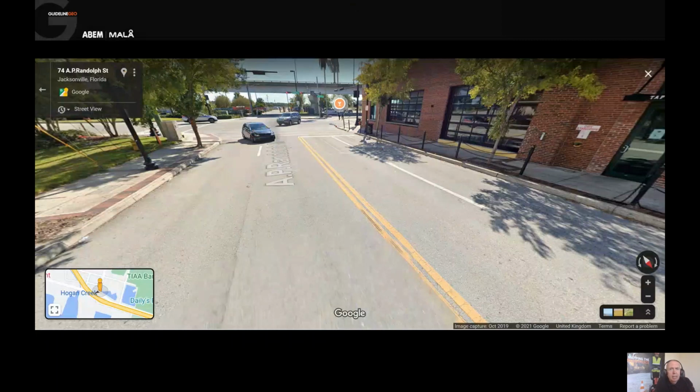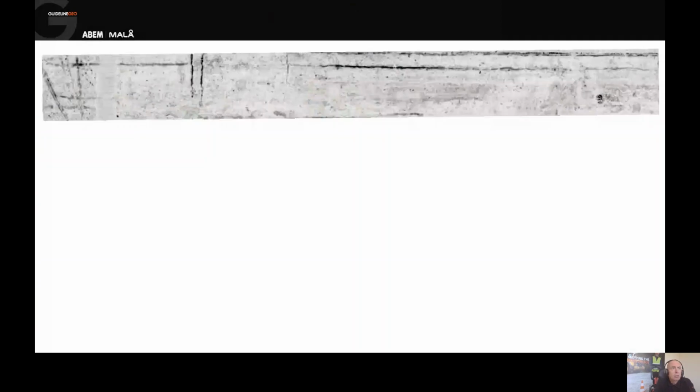So just ahead of any works or any tender for this work, we're going to go out and use the GPR. This was a bit of a trial. We picked this side road here, and we collected the data in just half of this roadway, to look at the performance and the response of the GPR data. We did deploy EM technology as well, to cross-reference and look at the amount of information that the GPR would be providing. Like I say, it was the array data.